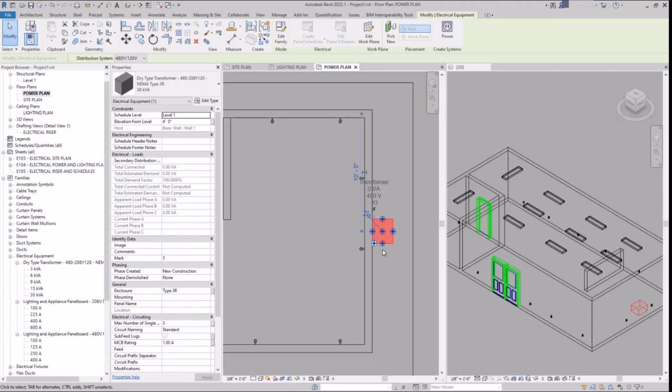That's how I did it. Oh, okay. I do it 30 kVA divided by 480 divided by root 3. Never thought about taking 480 times that, but yeah, that works. So it's just dividing out 30 kVA divided by 480 divided by root 3. And you can plug that into any calculator and it gives you 36.1 amps or 36 amps.